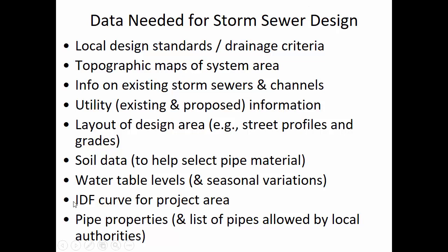And then IDF curve, we'll talk about that in detail today. The abbreviation IDF stands for intensity, duration, frequency. And that's an important way of characterizing the rainfall. It's essentially for a certain area how much rainfall you expect to see for a certain duration storm and a certain return period, or the probability that a certain size storm will occur in a given year.